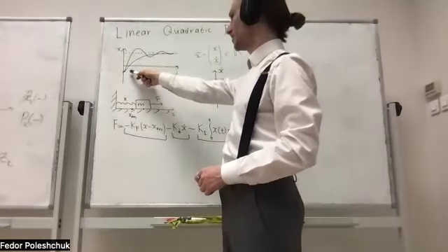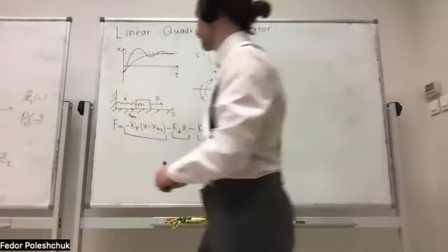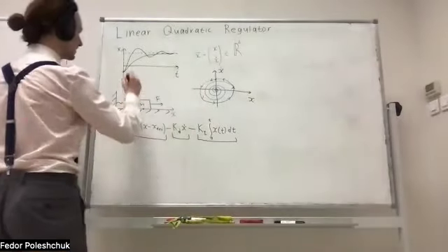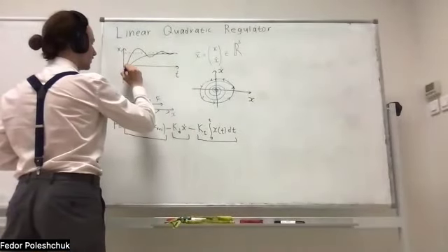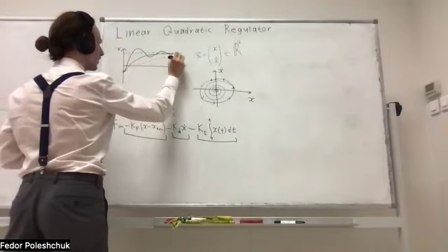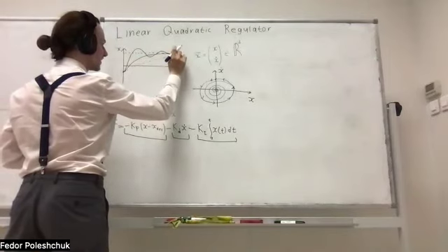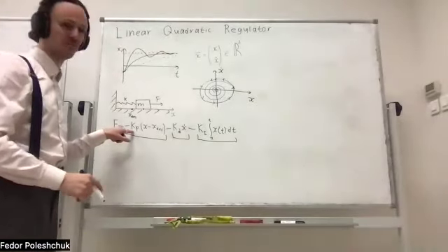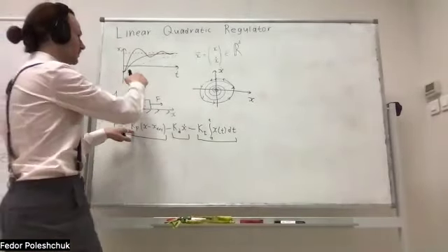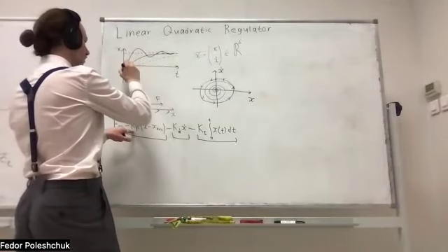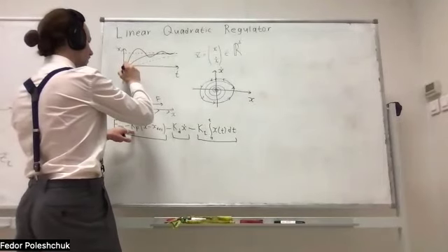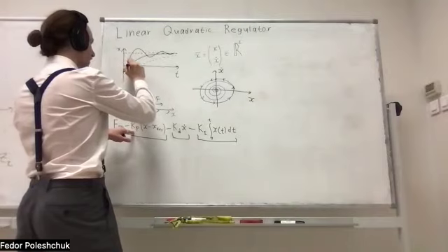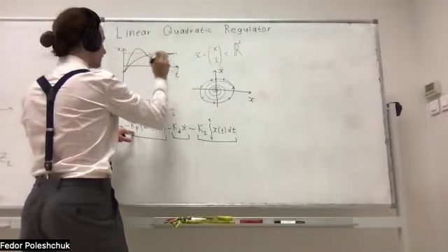We can observe the trajectory of the system, and if the trajectory of the system looks somehow like this, probably this behavior is suboptimal, and we can increase the P coefficient, the proportional coefficient. If we do that, we can approach the desired position faster.